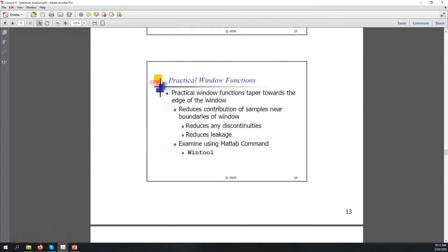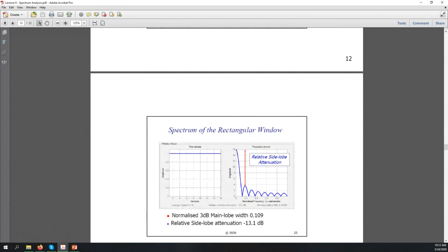For instance, with the rectangular window, because of the sharp transitions and the rectangular shape, you'll see that the relative side lobe attenuation tends to have some magnitude for the side lobe frequencies. You want to observe that for the first harmonic and then the second harmonic and so forth, you still have some magnitude, even though it's attenuated from the main lobe magnitude itself.